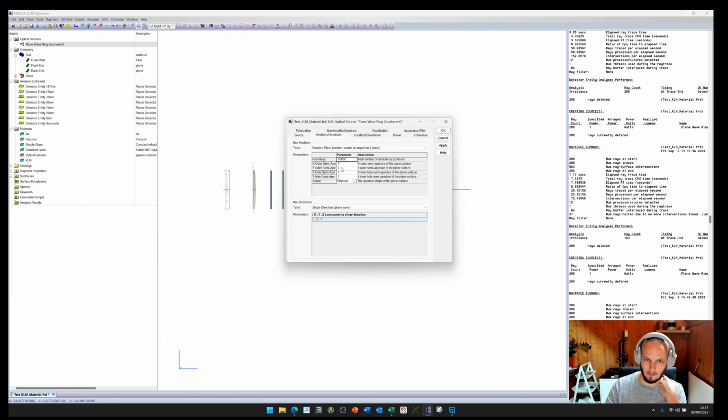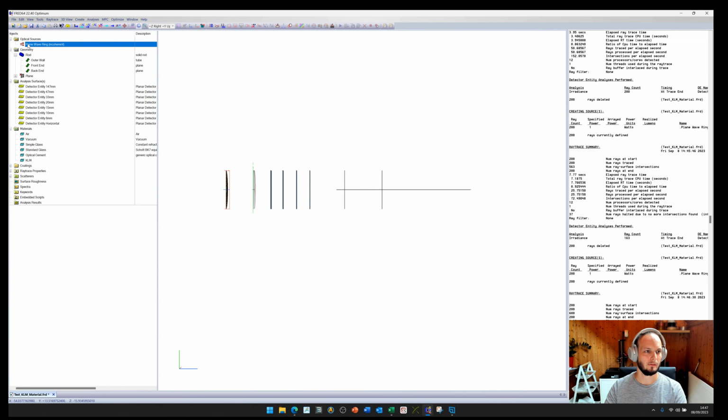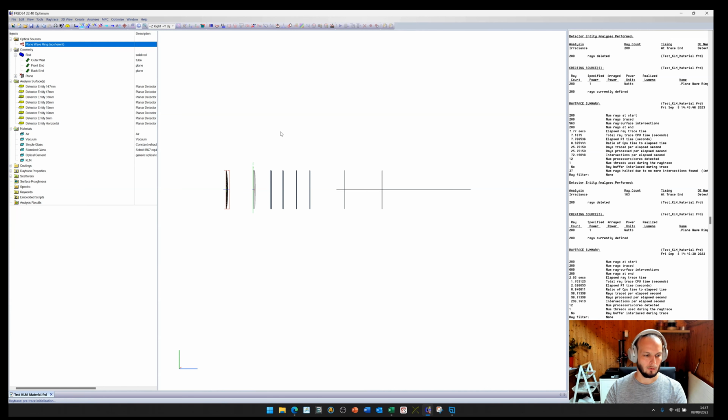You probably know about it, but I've chosen to leave the inner 1 millimeter of the source hollow, so it's basically similar to a ring beam anyway. If I click OK, 10,000 rays, and click save, I will trace this through. It will take about 16 to 20 minutes. After it's done, we can continue and have a look at what's happened here.